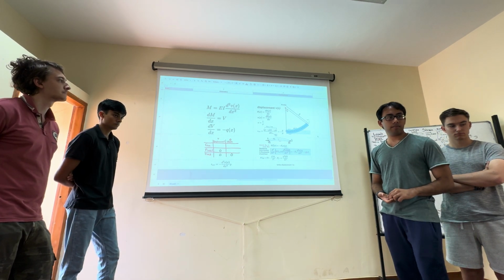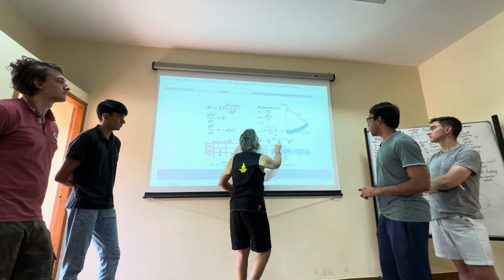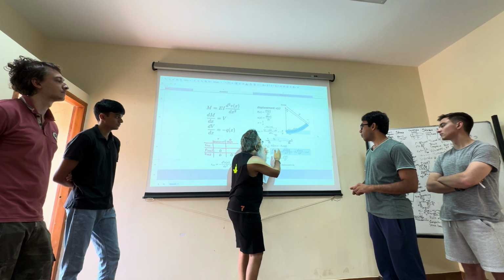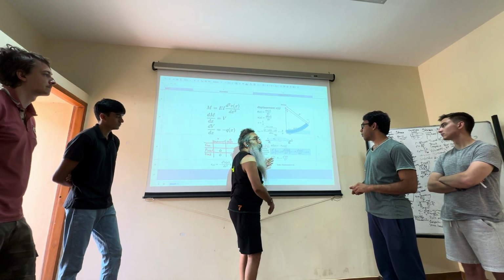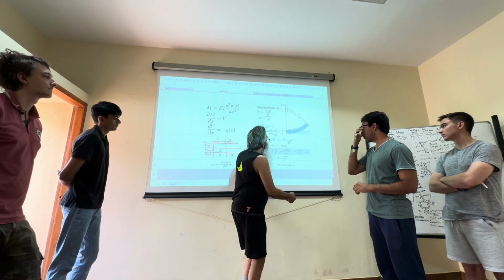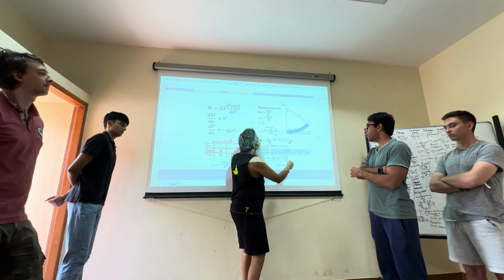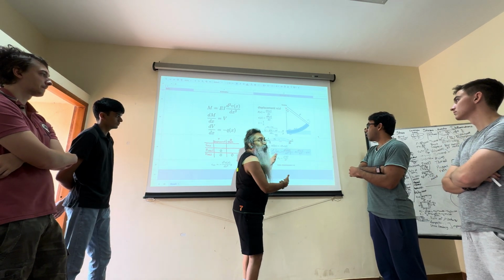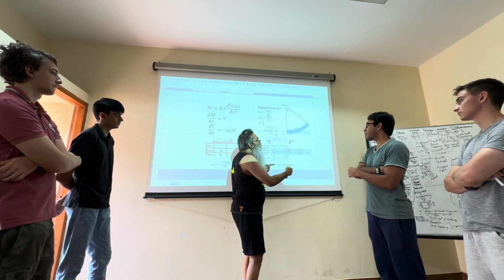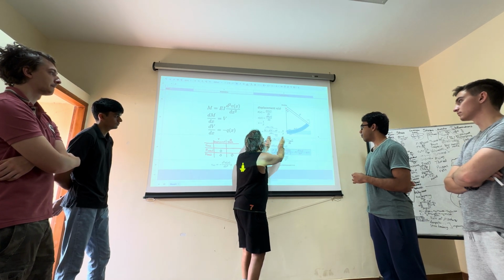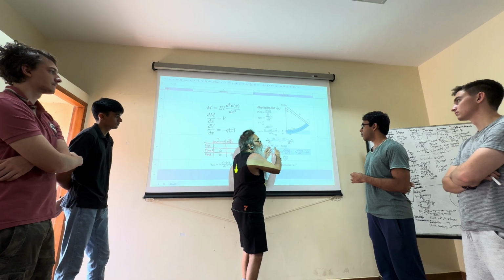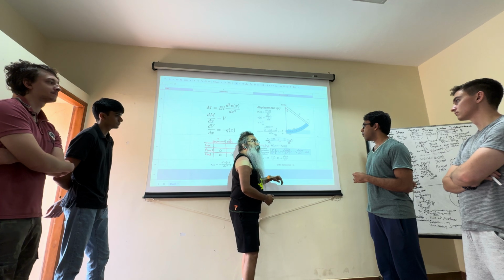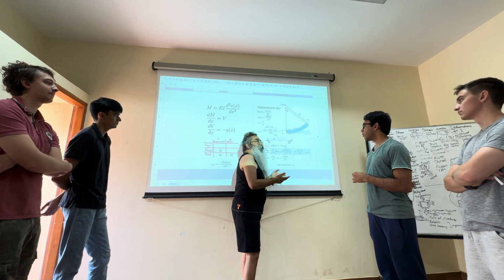Yeah, you mentioned that it's not only this load, but there's also some other load. It need not necessarily be. Even with just this load, you typically will have, beyond a particular value of that load, it getting into a buckled shape. The reason it happens could be multiple reasons. One is if these are not directly aligned to each other, there's a slight misalignment, because that could be an eccentricity with the load. The other could be in terms of the geometry. There could be an eccentricity because of the geometry, the way the structure is made. The other could be because of the material distribution. So once again, you could have eccentricity because of that.